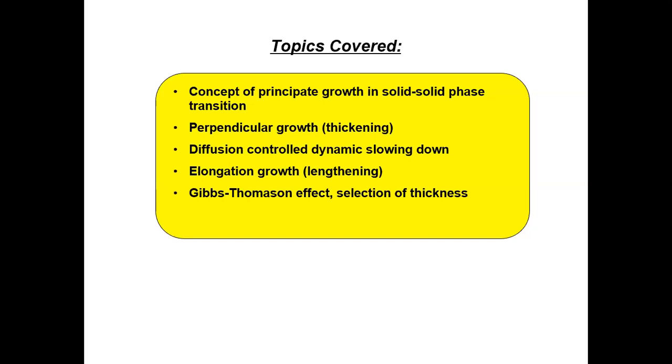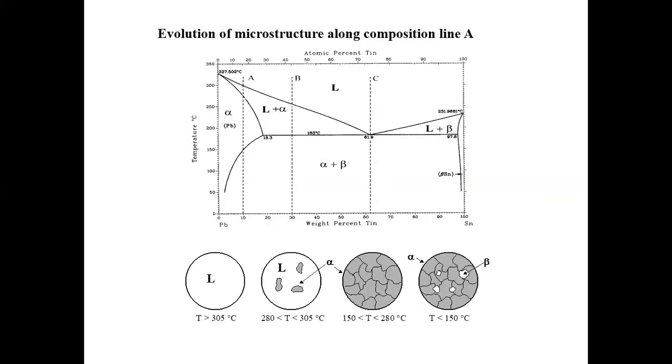Okay. And without going through all the mathematics, I think you already have an impression from the image we showed that the elongation is probably going to occur much faster than the thickening, right? Because you see that these black phases keep on growing along the grain boundary and trace the grain boundary. So the elongation growth is probably much faster. And this is indeed the case, as we'll show later in the lecture. Again, this is the second step in our discussion of solid-solid transformation or precipitation growth.